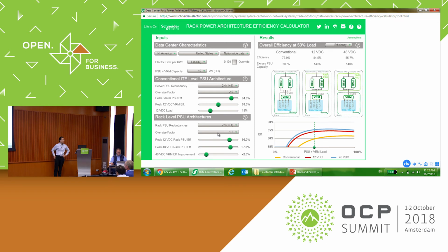There's also another architecture that we've been seeing crop up every so often that would be interesting to see. You've got 12 volt to point of load, 48 volt to point of load up here. The other one that's interesting is a 48 volt distribution through the bus bars and the power shelf with a 12 volt traditional motherboard. Colo, the telco, exactly right. Their distributions are all 48 volt, and rather than going 48 to point of load, they're going 48 to 12. Yep, I understand what you're saying. That would be the telecom architecture. It'd be interesting to see that as well. Thank you.